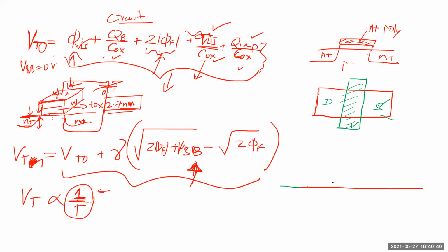So first you did all the processing steps and did what? You put the thin oxide and the poly together, and then use the mask to remove it, right? But this poly is an undoped polycrystalline. There is no doping, right? And then you take this mask and do the diffusion or ion bombardment and create the N plus, right?